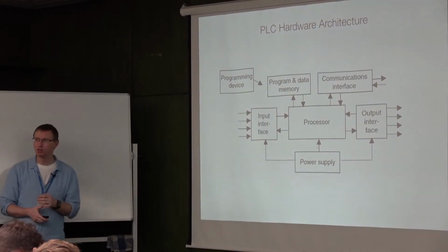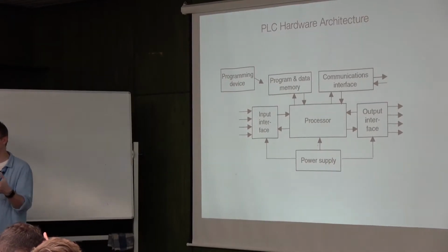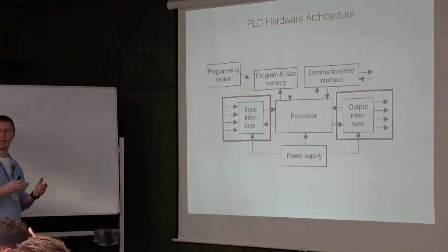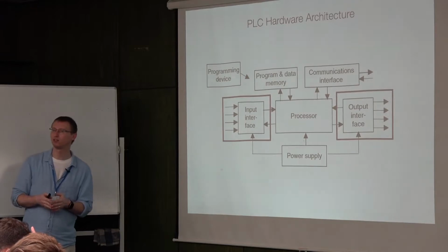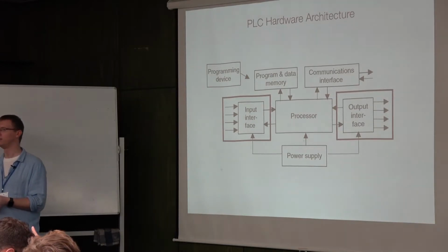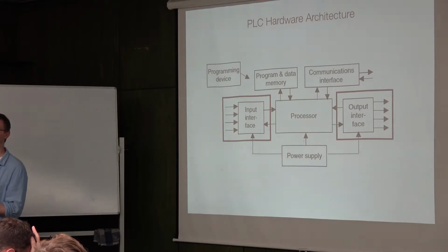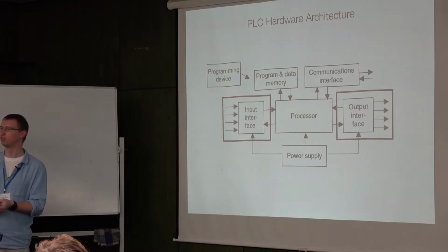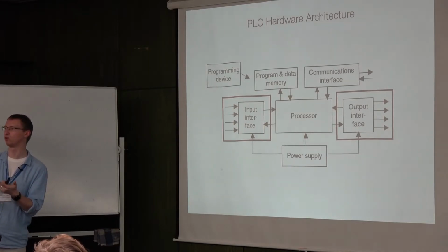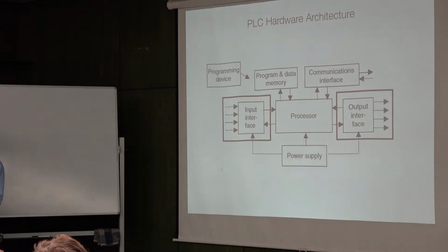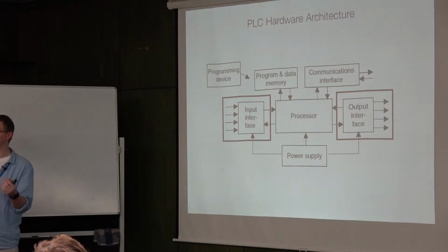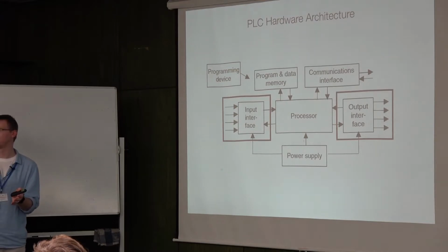Okay? So internally these PLCs are just a bunch of individual modules connected. We have input and output interface, and basically what makes the PLC so attractive for the industries is that you just take your standard sensor, which has some voltage or some current output, and you just plug it into the plug of the PLC. There is no need to have a USB port, a protocol, a driver, nothing like that. There are simply standardized voltage and current signals, so you can just take any standard accessory from your catalog and just plug it into the PLC and it will work.